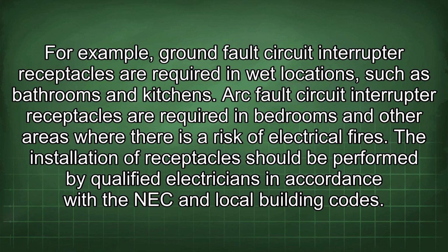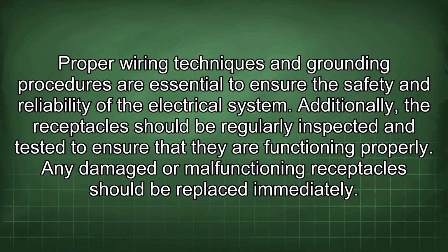Arc fault circuit interrupter receptacles are required in bedrooms and other areas where there is a risk of electrical fires. The installation of receptacles should be performed by qualified electricians in accordance with the NEC and local building codes. Proper wiring techniques and grounding procedures are essential to ensure the safety and reliability of the electrical system. Additionally, the receptacles should be regularly inspected and tested to ensure that they are functioning properly.